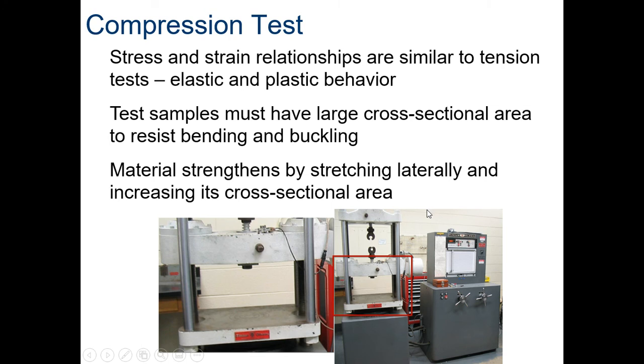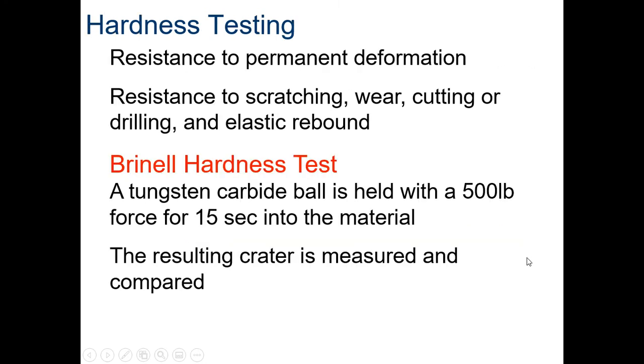Now, the compression test is the same thing, except we're not pulling them apart. We're pushing them together. But it's almost similar when we do the compression test. Think of concrete, which would have a compression test. For bridges, you would have to have a compression test. If the bridge failed, you check the concrete. Maybe they put too much water in, not enough sand. There's a whole lot of things that could go on.